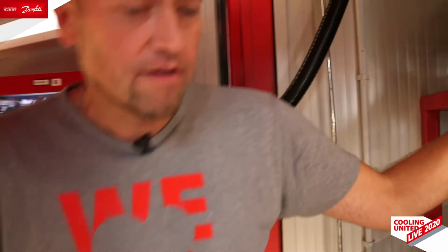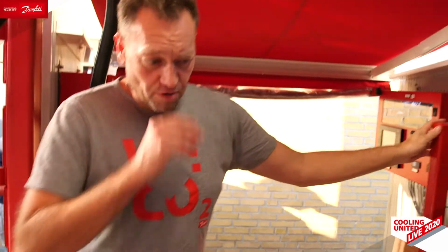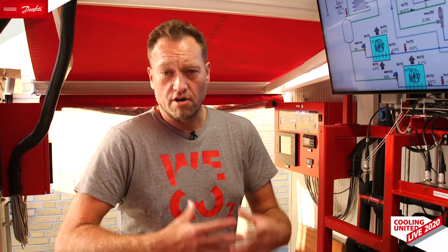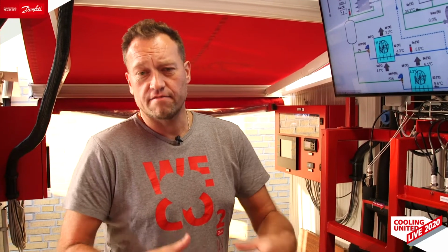But let's first have a little look at the efficiency and also the first cost aspects of this, because we are introducing new components, and this means that the first cost of the installation goes up, but with the CALM system there is a very low payback time on this additional investment. Basically, the reason why we can deliver a good return on investment with the CALM solution is that the liquid that we have in the system is very, very limited. We are not running the system flooded as we know it from traditional ammonia systems on the industrial refrigeration side.